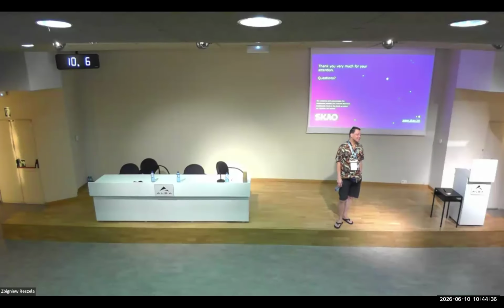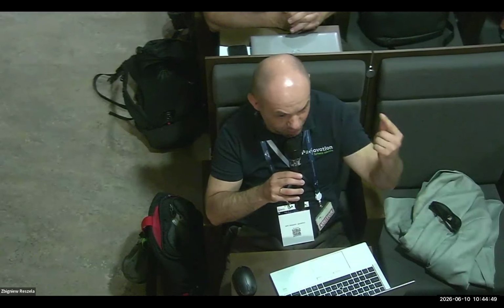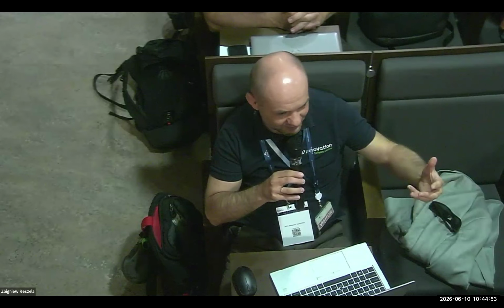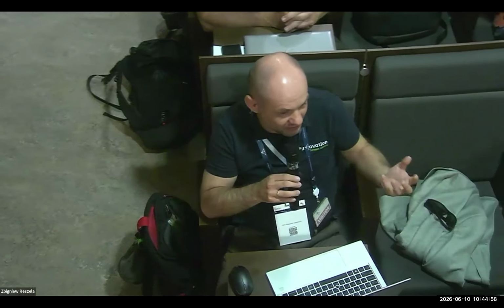I have a question. Thank you for the presentation, it was great. It is a question about the processes, rather. Do you already have some alarm policy which prevents so-called alarm floods? Because you can have a very fast notification period, let's say 1 second. But if there are more than 10 alarms at the same time, the response time will be much longer because the operator will not know what to do.